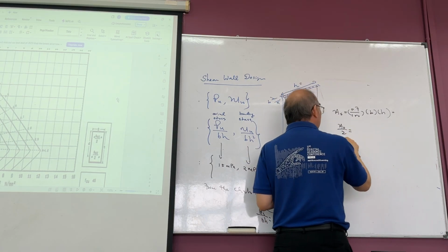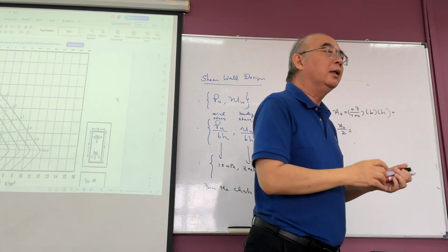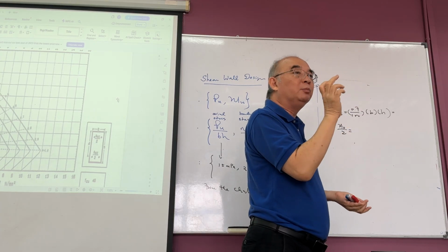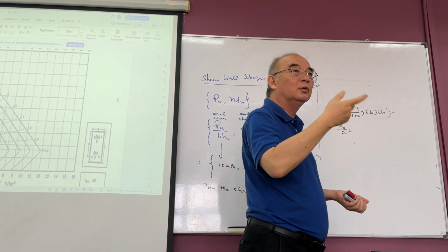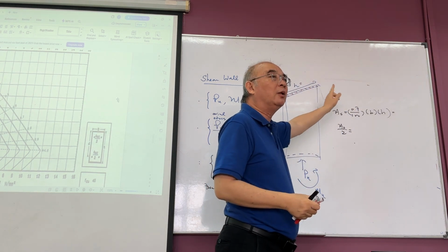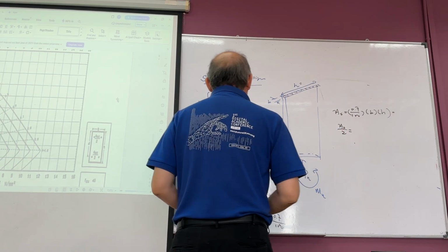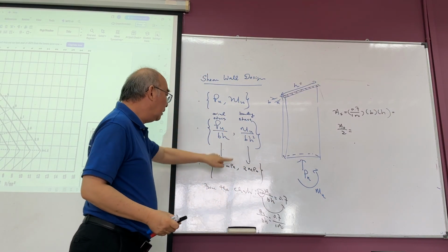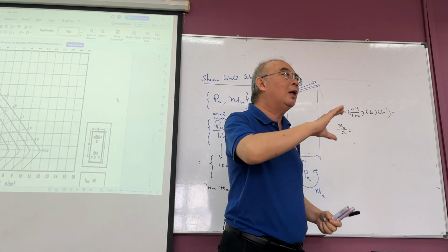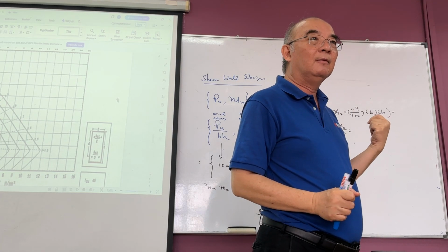This is total, so this is per row, right? Per row. And then you have to divide it by this length. That means each row, each meter, then you convert it to the number of bars. Because eventually we need to tell people, is it a T12 at 200, T12 at 100 per face, per row. Understand? Okay. So if this is given to you over here, then this is very easy, right? At least you can get to here first. Whether you can know how to convert it, that's a different matter, but at least you already get most of the marks. You see what I'm saying?